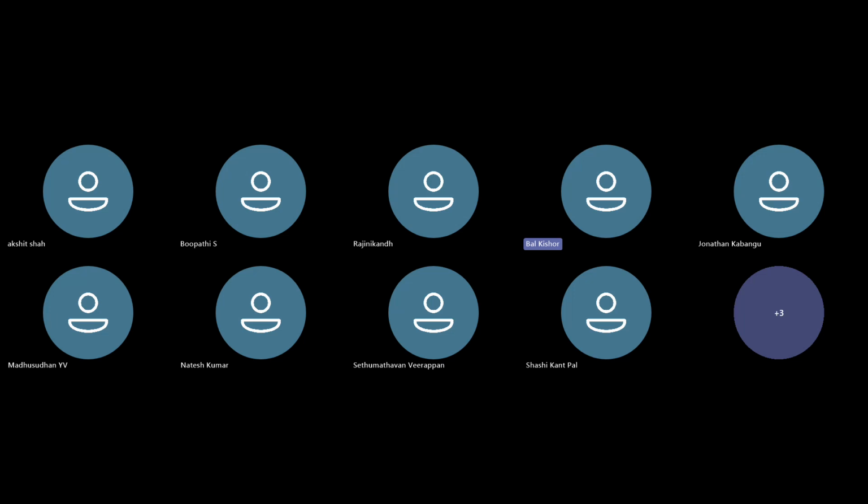Okay. So let me go here, configuration, increase the simulation time. Let us say 10 Hertz, right? So it means 1 second, 10 pulses. So 0.5 second I will run, so 5 pulses I can get easily. You have to calculate that. It's very common practice. So you can see I have 5 pulses in blue color, and the red color is the clipped voltage, right?